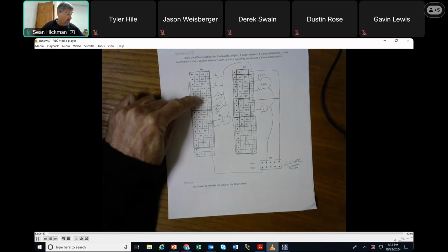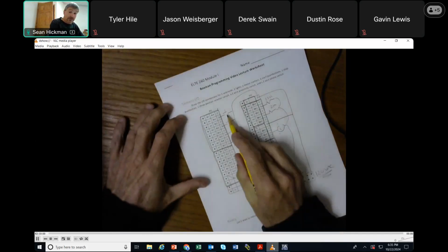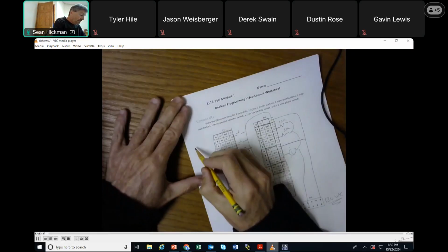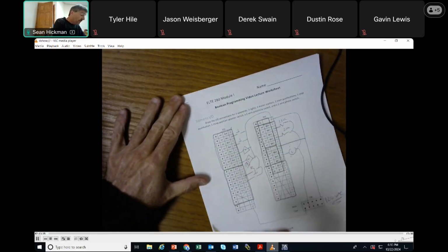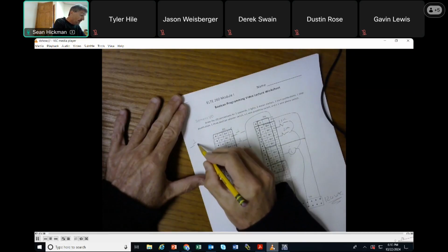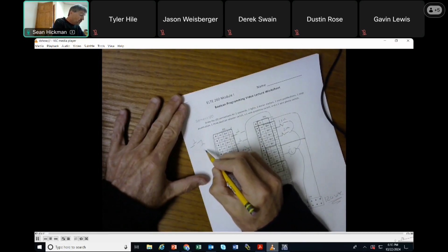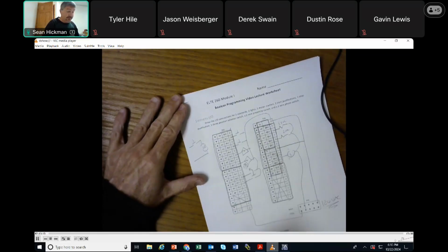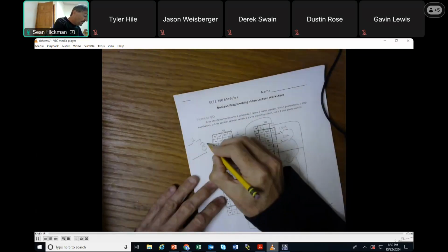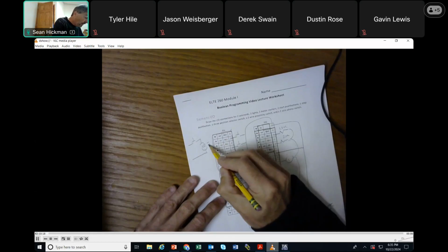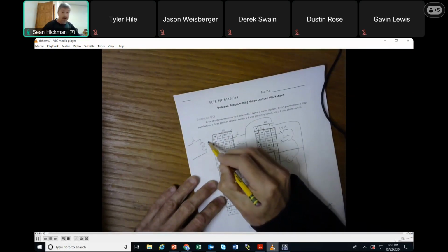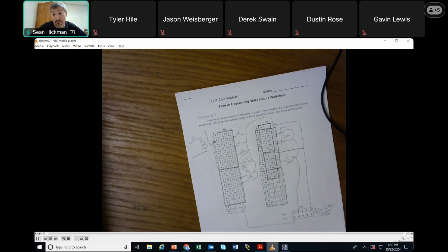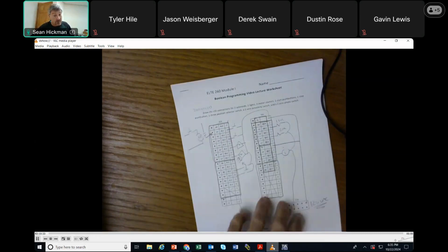That's what this is. So really what we've got going here, when you push this button, by the way, and this is not truly what we've got going here, it doesn't matter. What we've got is when you push this button, we turn on a control relay. That's the way that we've got it. And then the contact from that control relay is what is wired into that input. So when you push the button and you hear all this clicking going on on your training station,